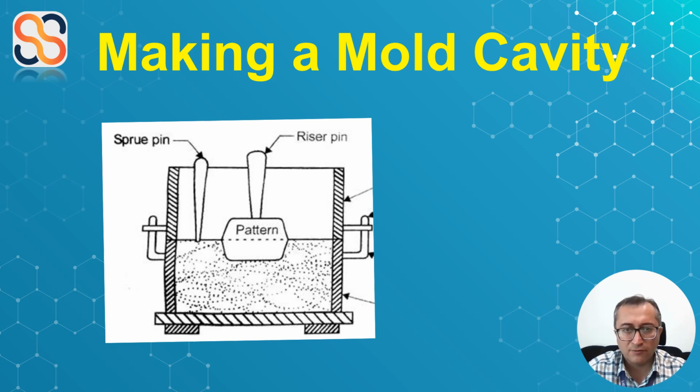If necessary, we can set gaggers in the cope at approximate spots. Just remember not to place them too close to the pattern or mold cavity, or they might chill the casting. Once we have everything in place, we fill the cope with molding sand and ram it uniformly. Next, we strike off any excess sand from the top of the cope.